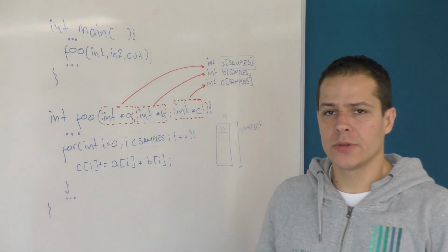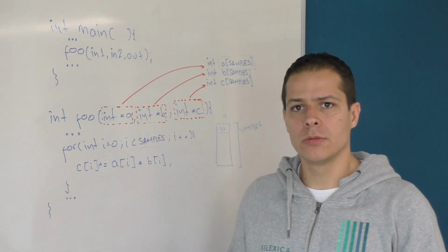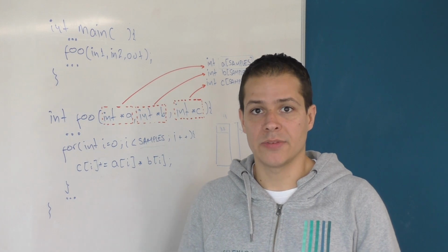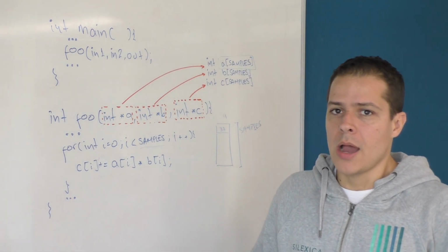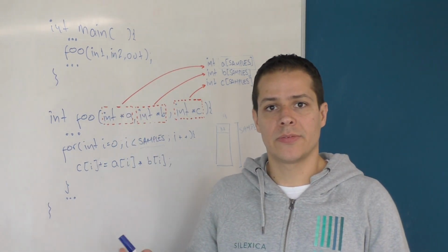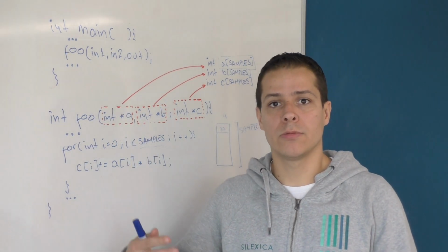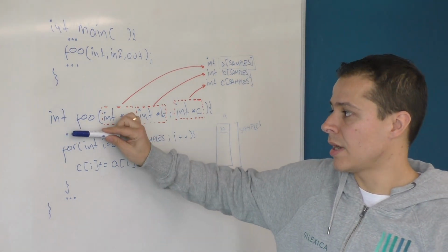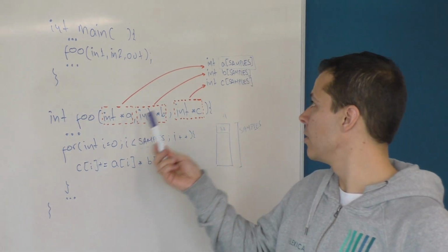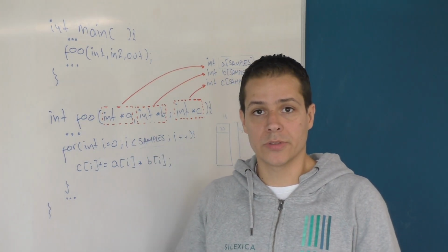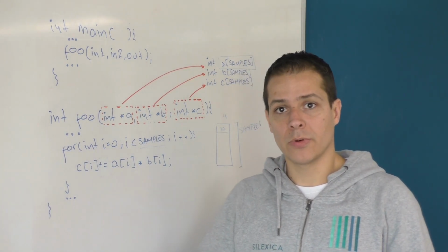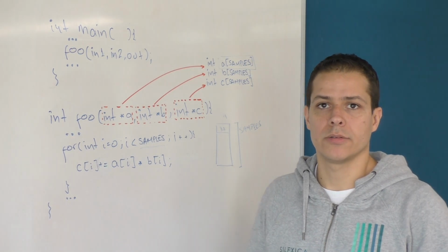So for example, you could have a chip that's going to do some computer vision algorithms, and you need to connect it to different cameras, which will have different formats. Now, what a designer would do is make this code and fix the arrays, so fix the different formats that the algorithm needs to work on, introduce or adapt the functionality of the chip via C code, which is still synthesizable because it knows the size of the arrays it's going to be processing. And then the implementation that the HLS tool will produce for this chip will already take this into account.